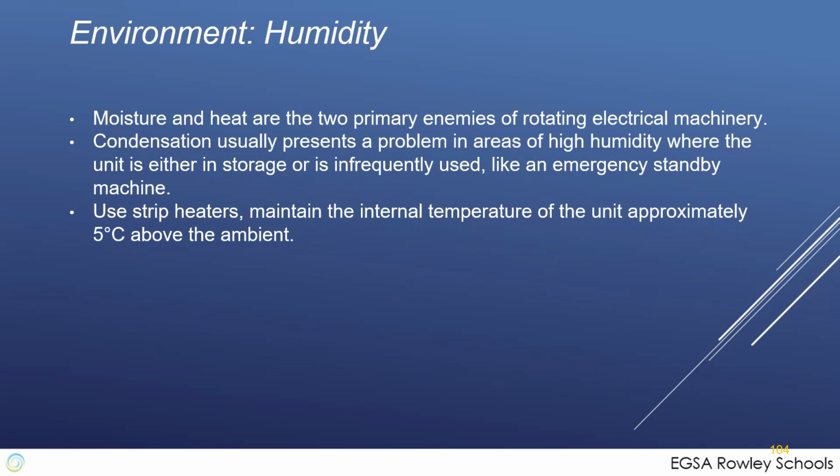Humidity is less and less of a factor today than it was in the past. Today's insulation systems are less dependent upon organic compounds like paper and more dependent upon plastics as the insulation material. So it's not as much of a problem, but still you should have strip heaters in condensing atmospheres in cold climates, just to keep the temperature of the generator a few degrees above ambient. Turn them off when it runs.